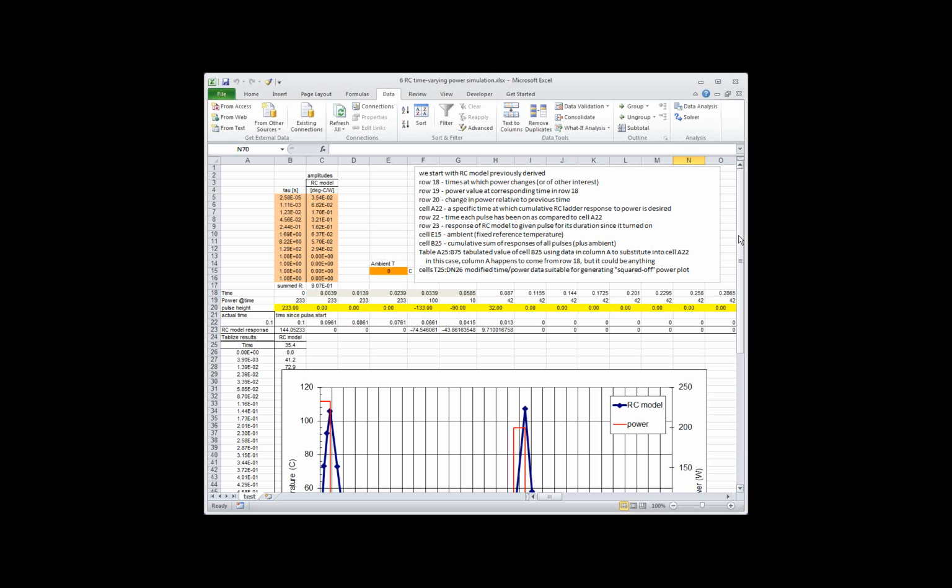Okay. How do you control the short time response of an RC network model? Well, as we saw in this demonstration here, you can make the RC model fit a square root of t. You just have to pick the time constants. Once the time that you're trying to match falls below the shortest time constant of your RC model, you will not be able to do square root of t.